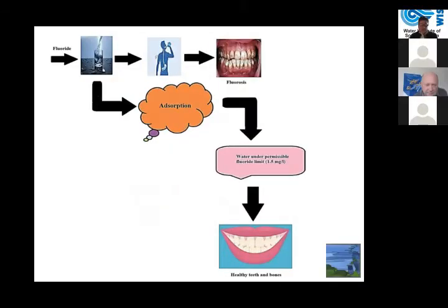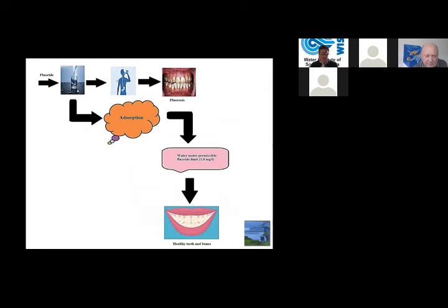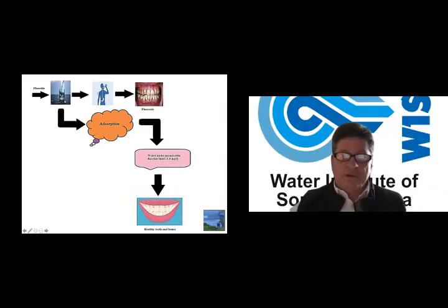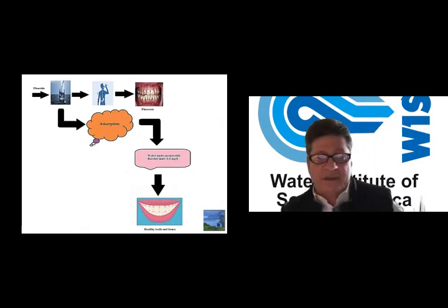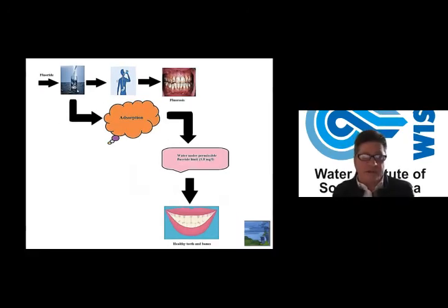So in terms of fluoride, before we look at the options for fluoride, I think you're familiar with the causes of high fluoride in the water. Anything above about 1.5, you can get serious fluorosis. You can get mottling of the teeth, brown formation on the teeth, but you can also adversely affect your skeletal system and get brittle bones and bones that break very easily if you drink water with high fluoride over a long period of time.